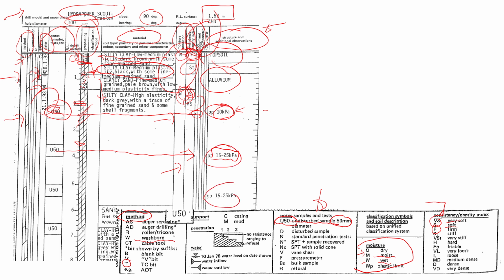So if I look at this borehole log and then I look at this part of the cross-section, this geology, I would say that this material is a very soft clay. It was originated by river because it's alluvium, and it's very wet, very soft. So this is going to be a big issue with construction, with any engineering design.